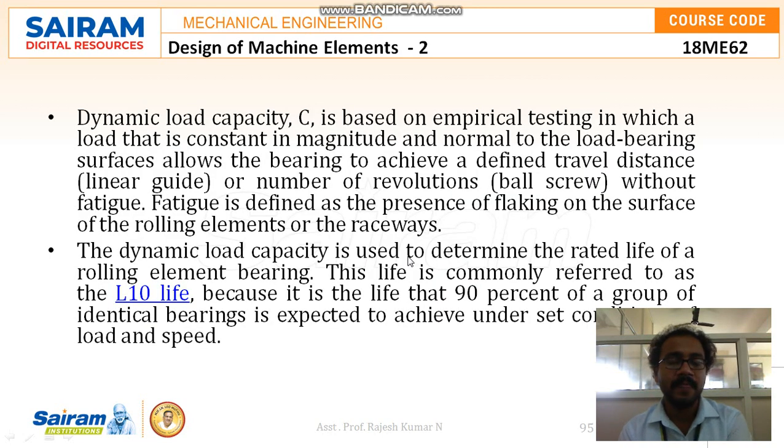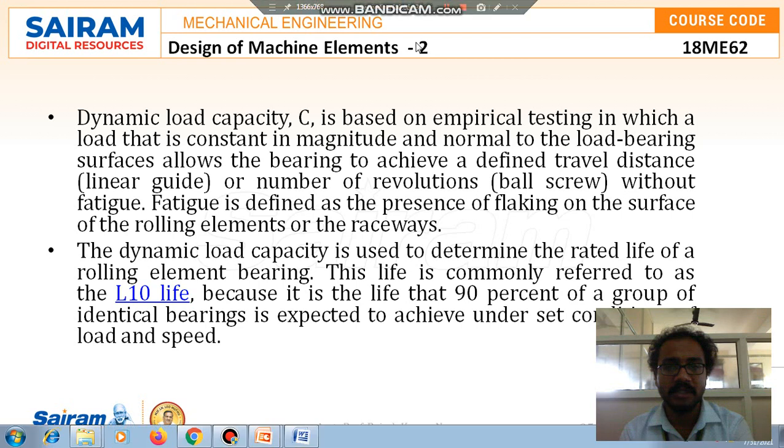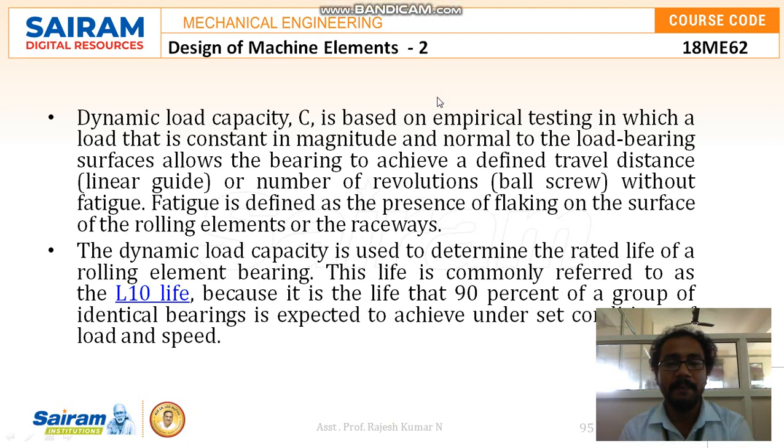Moving to the next one, the dynamic load capacity, usually denoted as small c, is based on empirical testing, in which a load that is constant in magnitude and normal to the load bearing surfaces allows the bearing to achieve a defined travel distance, that is a linear guide, or number of revolutions, in the case of a ball screw, without fatigue. Fatigue is defined as the presence of flaking on the surface of the rolling elements or the raceways.